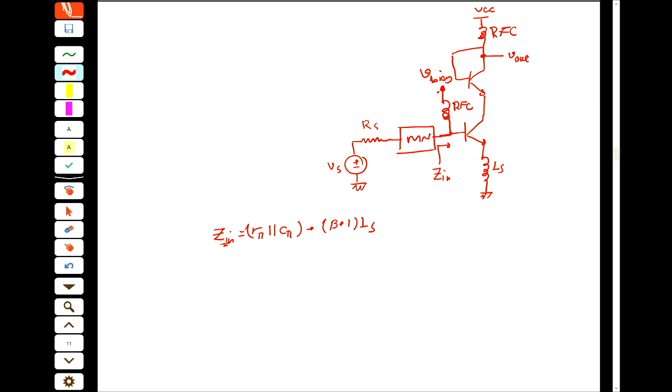Again, we use two transistors. This transistor Q2 is for increasing the isolation. One thing that I want to mention here is that if we want to block the DC, I want to block this DC going to the previous stage and block this DC going to the next stage. Why would I like that? Because I don't want the next stage or previous stage DC to affect the biasing conditions of my stage, and I don't want my stage affecting theirs.